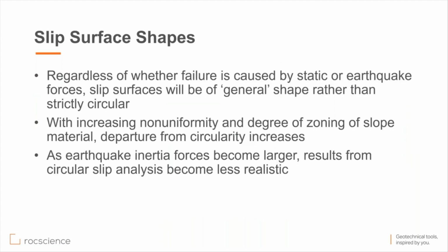Now, when doing slope stability analysis, we also talk about the shape of the failure surface. Originally, the methods all dealt with circular surfaces. In 2D, these are circles. In 3D, that will be spheres. With time and with advancement, particularly with the advent of computers, we now do non-circular analysis. So for most of this discussion, we will be focusing on methods that can analyze non-circular slip surfaces as well,